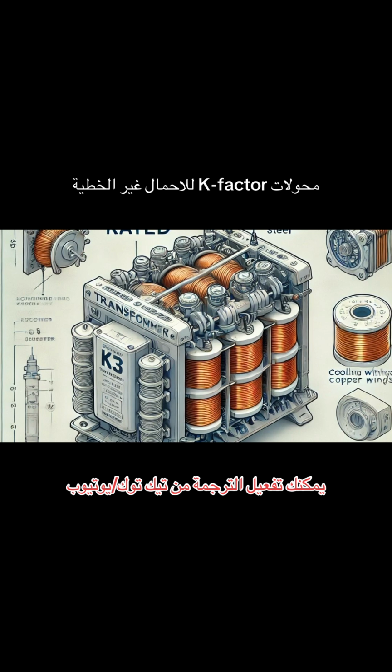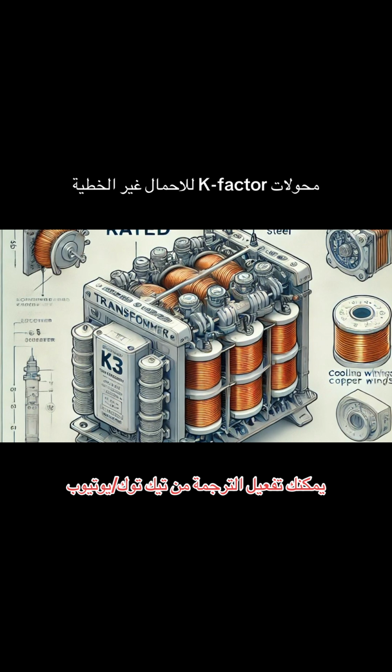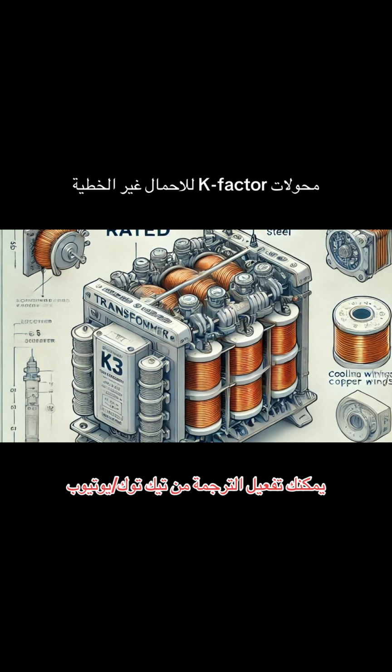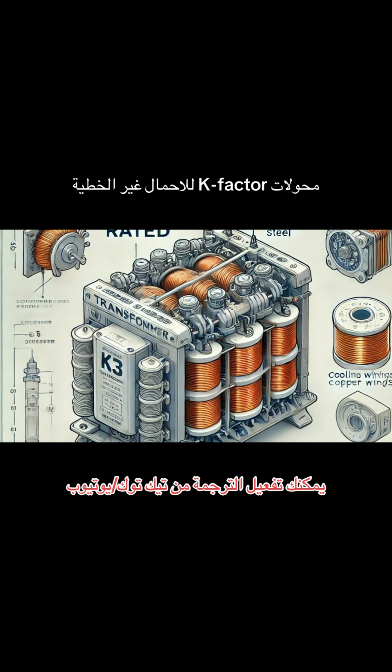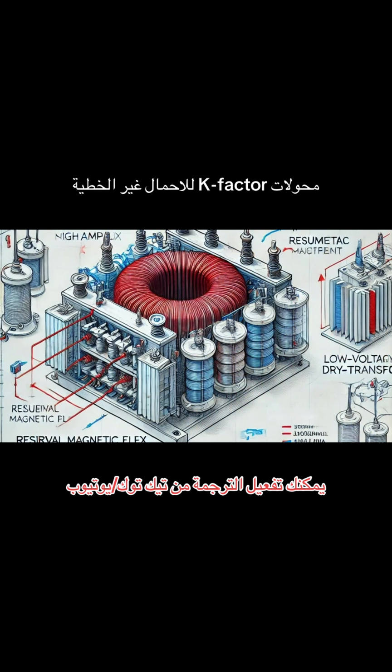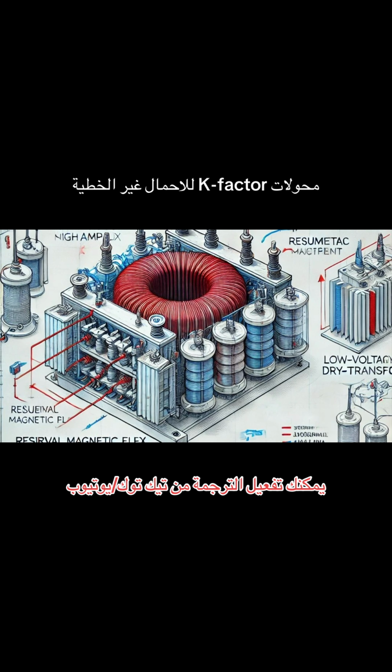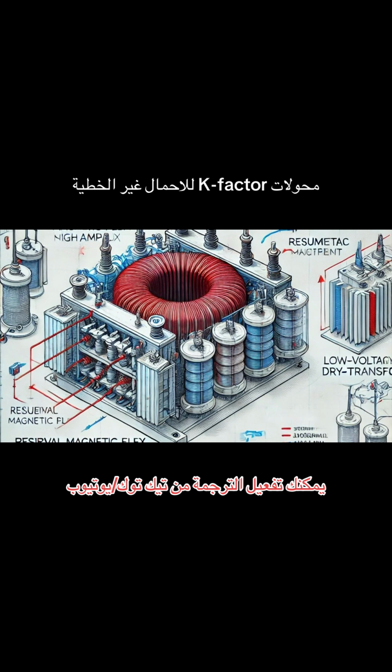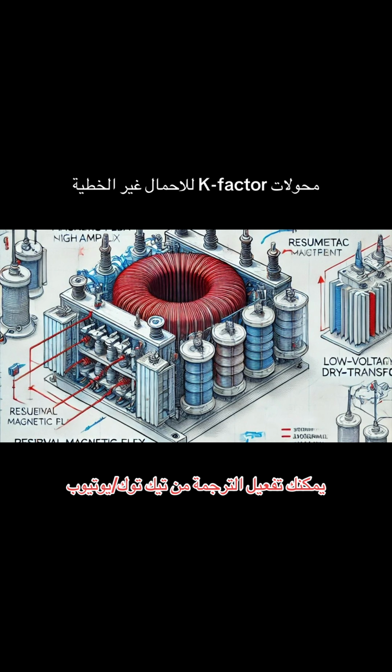Well, one of the biggest things, and the paper really stresses this, is that they have a much larger neutral bar. It's beefed up compared to a standard transformer. In fact, there's this key safety standard, UL 1561, which mandates that K-factor transformers have a neutral bar that can handle roughly double, yes, double the transformer's full load ampacity. Wow, why is that extra capacity so important?